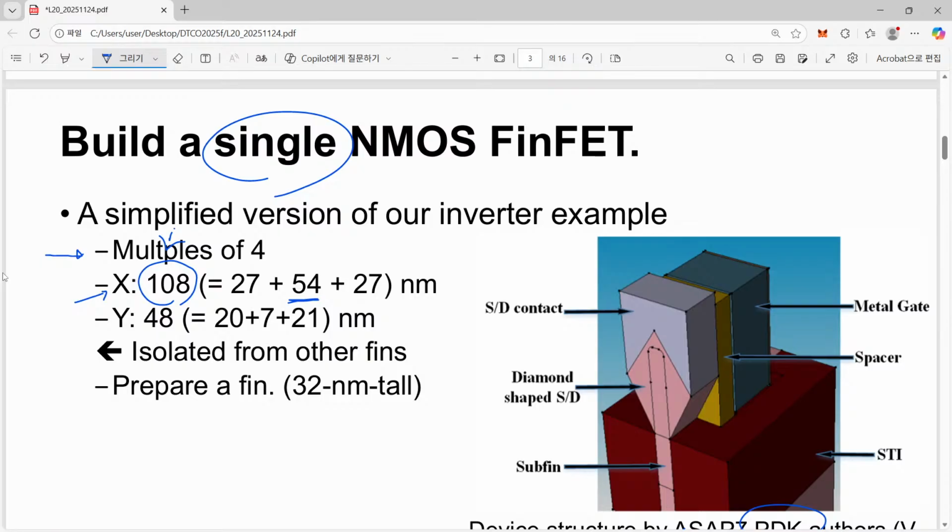Why did I do that? Because I wanted to consider the shape of the source and drain as exactly as possible. If we cut somewhere except for that spacer region, then the source drain epitaxial growth is distorted, and I was not able to get a similar behavior.